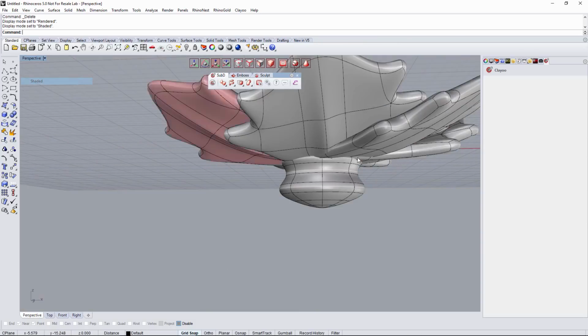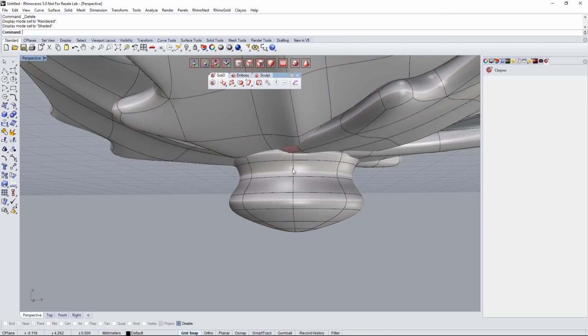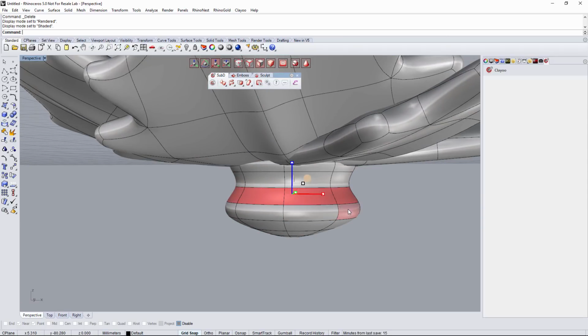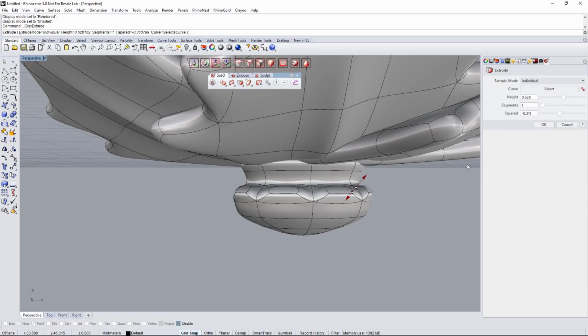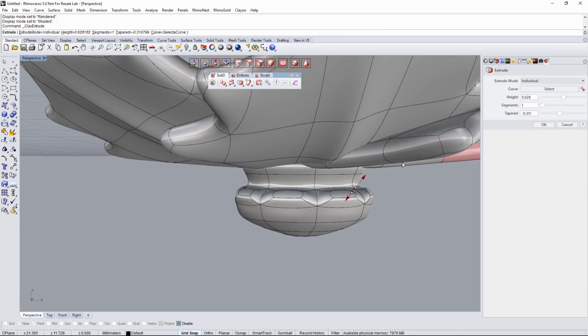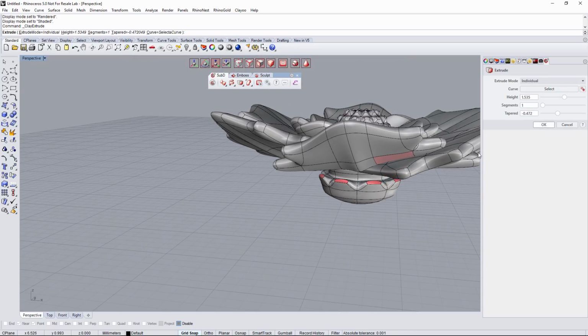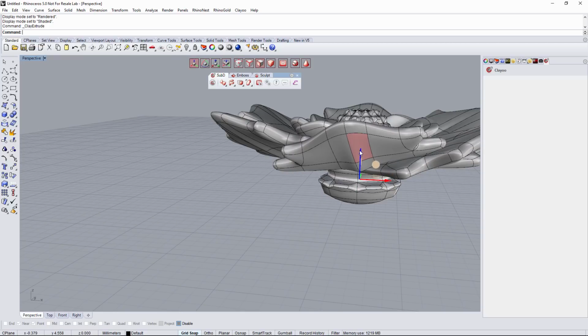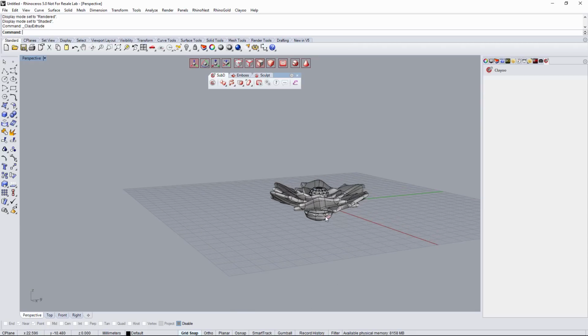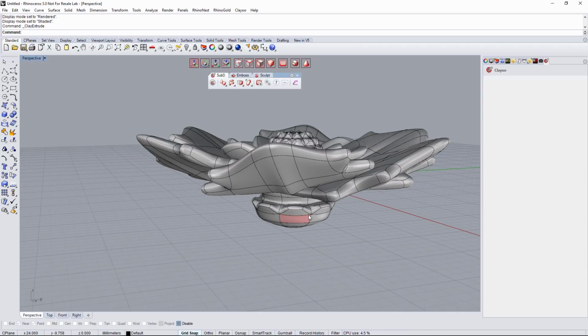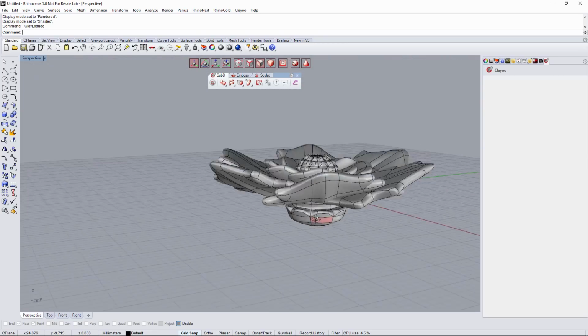And if I want to add some more details here on the bottom part, I can just grab, for instance, all these faces in there, and I can extrude them. In this case, we set the last settings that were individually. You can refine a little bit more the taper value, something like that, clicking on OK, and I can refine the positioning here if I want to look up or look down, but it can give you a small effect in here that can be really nice in some cases.